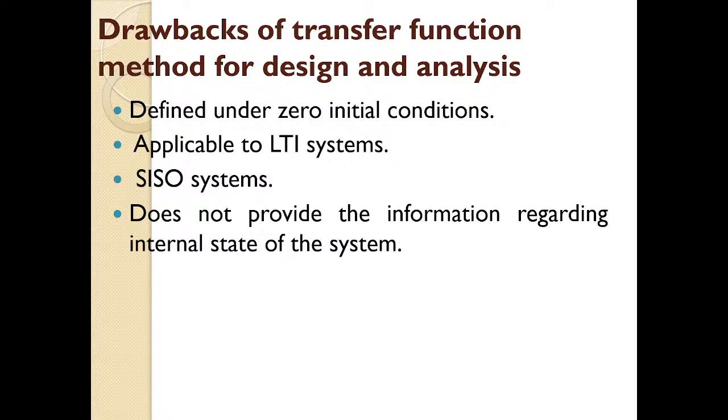The drawbacks are: the transfer function is defined under zero initial conditions. That is one of the drawbacks. And the transfer function is applicable only to linear time invariant systems, and also only to single input single output systems. And the transfer function won't provide any information about the internal state of the system.